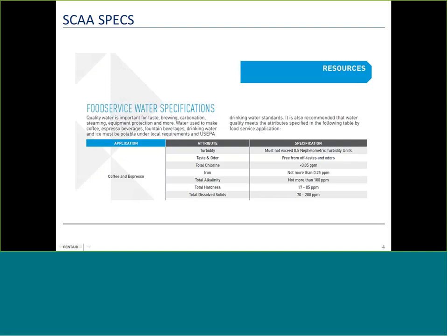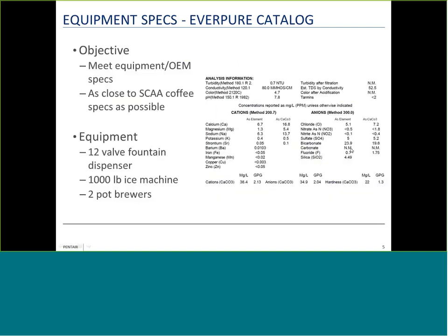So in summary, basically what we need here is carbon-based filtration for either chlorine or chloramine to remove its taste and odor impact upon the beverage quality and any potential corrosion it could cause in the coffee brewers. Ice is all in spec. The only thing we really need to do there is chlorine or chloramine removal for taste and odor control, and use phosphate for long-term scale protection.